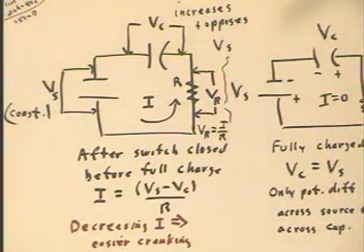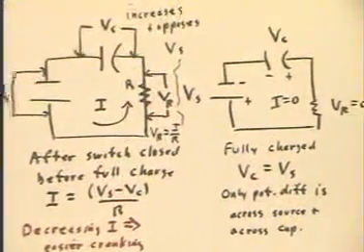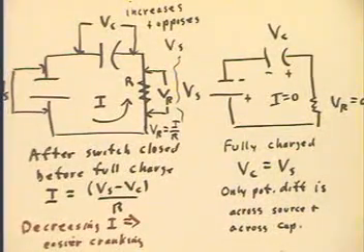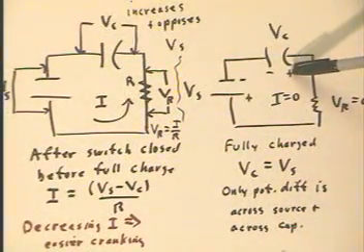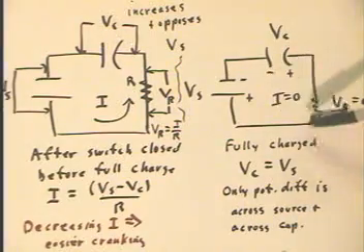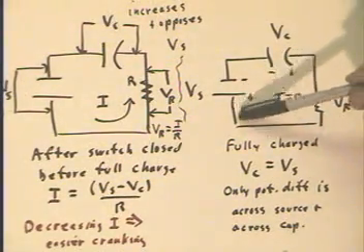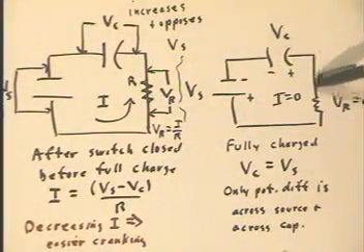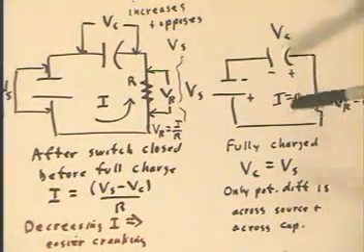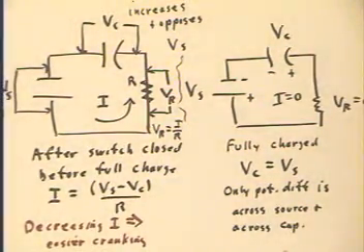When the capacitor gets fully charged, we have a voltage across the capacitor, positive here, negative here, which fights the voltage across the source, positive here, negative here. The positive here wants to push this way, positive here wants to push this way. We get zero current, which means that it doesn't take us any effort to crank the generator. There's no demand placed on the battery.